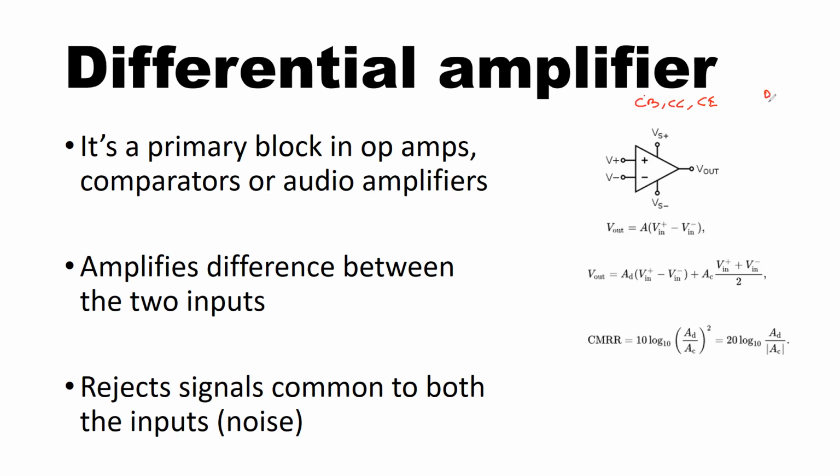For example, you had this positive V supply, and then you had this resistor, and then there was this BJT, let's say transistor Q, and we used to take output from this collector. This is the NPN transistor. Then through some bias, you apply a base voltage to the base of the transistor. The resistor at the emitter to the ground is called resistor RE, the emitter degeneration resistor.